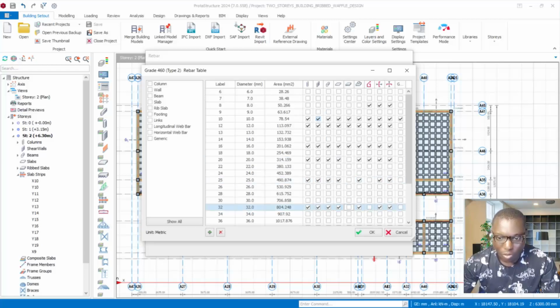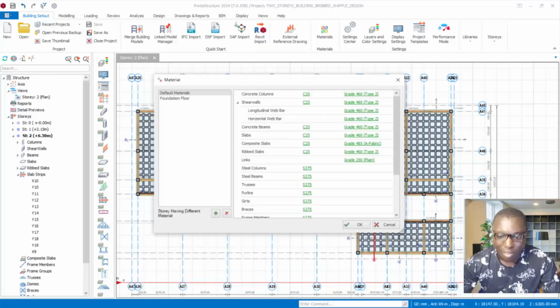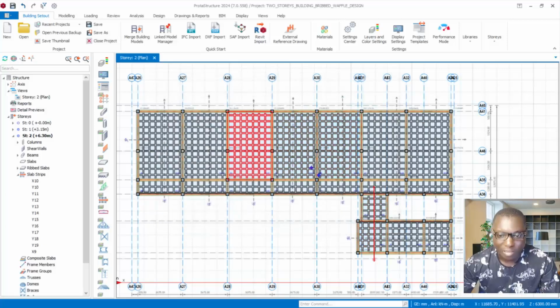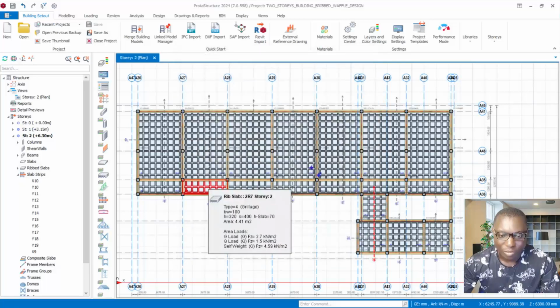Okay. So all of this may be selected for columns and beams, okay, but that is not our concern for now. We are actually concerned about the ribs. So you can see we have chosen this for the ribs slab successfully. I click on the OK options right here, and I click on OK. So we have actually reset the materials. We save it from these provisions successfully.